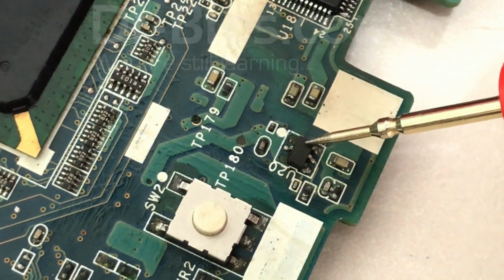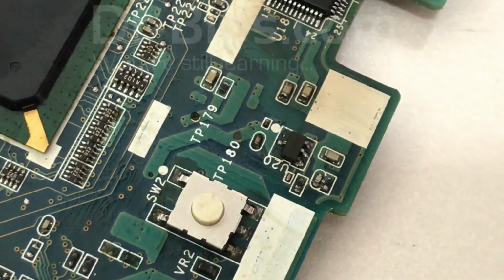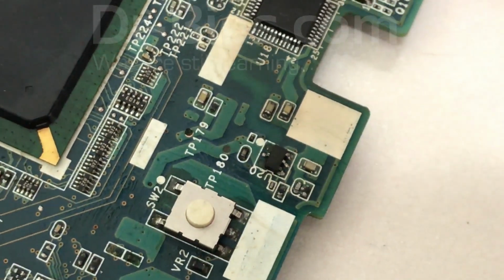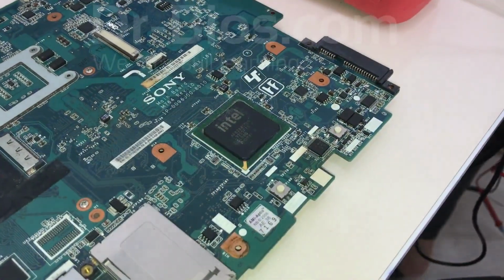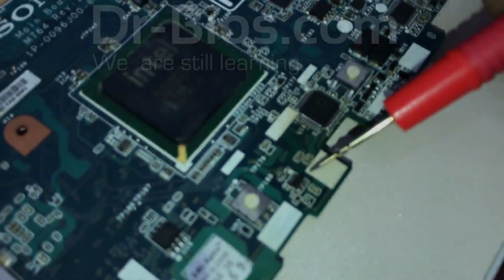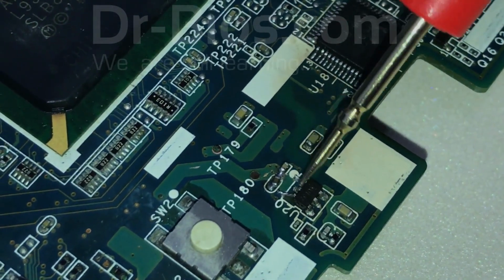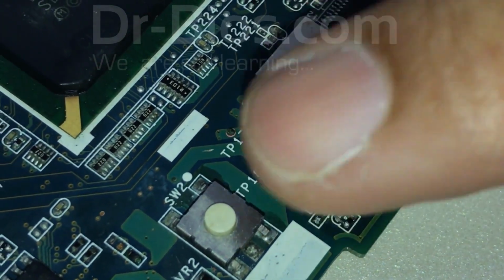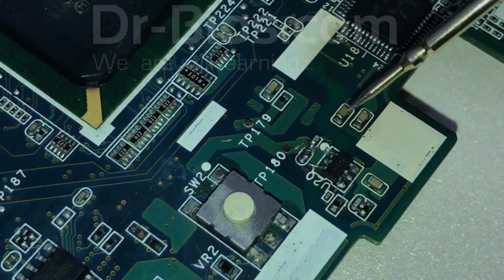I should say that voltage doesn't enter the IC. Because of that, there is no output. So I only change U20 for now, so that 5 volt analog will be provided. I didn't find the IC, so I removed the rust of the pin. These pins were rusted. It might be because of moisture infiltration on the touchpad. This part was rusted.